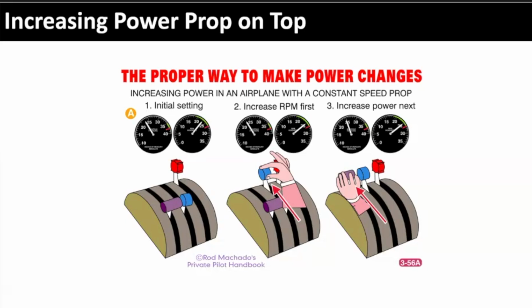Some people will argue that in these training aircraft, that's not a huge issue. If you're in a smaller Piper that's got a constant speed propeller, you're not going to cause damage to the system and the propeller with an overspeed situation. Again, lots of lines of thought and lots of different arguments, but if you're going to do it, advance the prop first and reduce the manifold pressure first. All right, way more than everybody wanted to know about constant speed propellers. It's all in there.